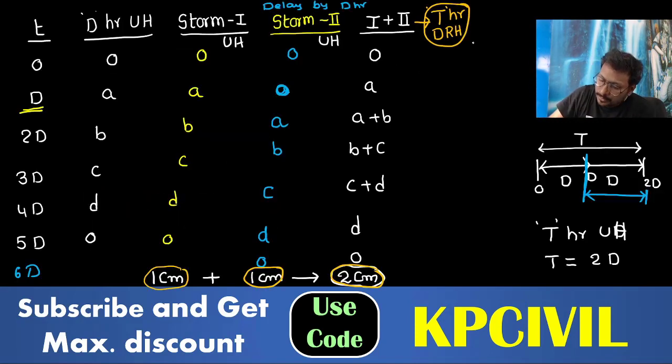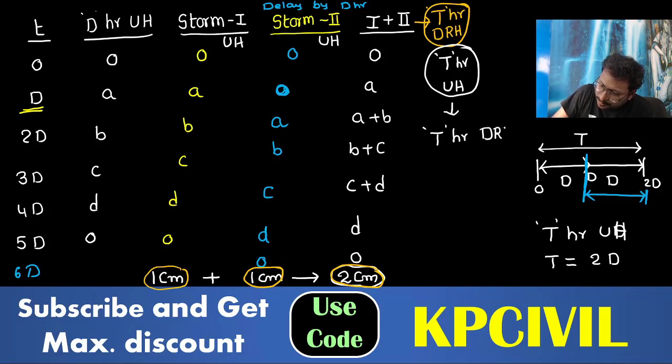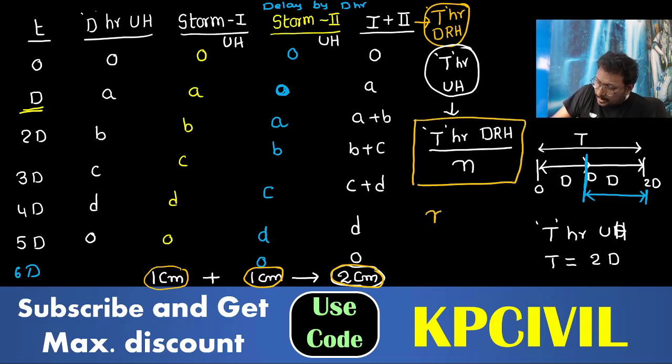Then if you want the T hour UH, how can you calculate? Simple. T hour UH is equal to the T hour DRH, which you have obtained in this last column, divided by N. What is N? N is equal to T by D, total duration by UH duration.